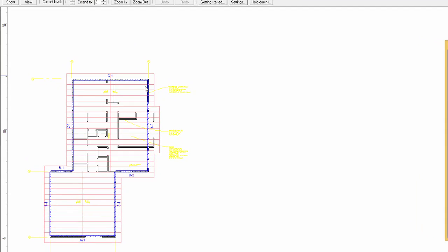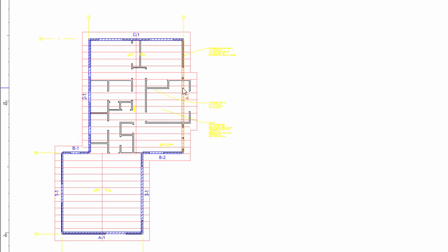Select wall 4-1 and separate it into 3 different segments by drawing an intermediate segment. Next, hold down Shift and select wall 4-2 to extend it. In order to limit the unknowns, we will choose the following properties for all the exterior walls with hold downs.